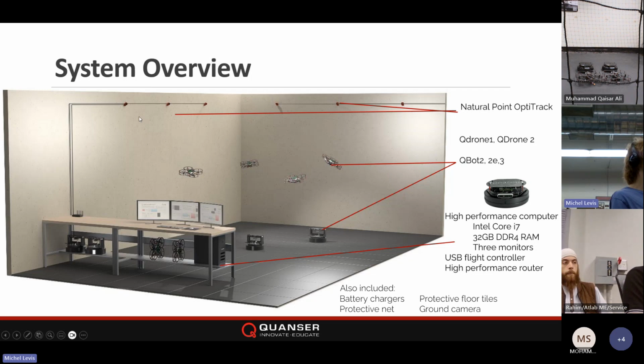The other thing to remember is for these OptiTrack cameras, it's important that before you do calibration, before you do anything with this localization, to turn the cameras on for at least 15 minutes. The cameras are on. You mean opening the software as well? That's correct. The cameras go on, and you know that because the LED goes on the camera, and you do that by opening the Motive software.